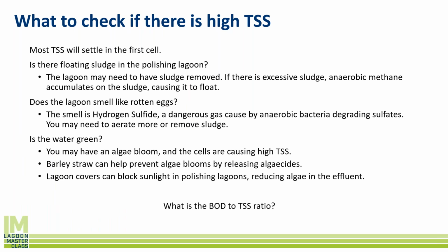If it's happening upstream in your facultative lagoons, you probably need to add more aeration to help dissolve those sludge blankets, or go ahead and dredge those ponds. But we all know dredging is very, very expensive.